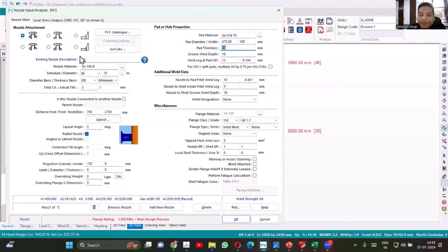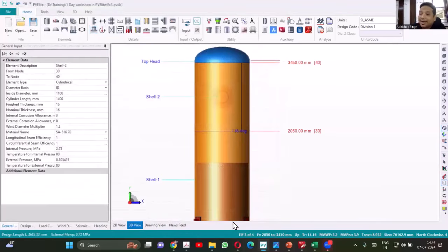So let us start from this point and go down. Then we'll go to RF pad. So this data is clear. Now I'll go to where I want that nozzle to be. You can change it, that is a selection. Normally we make nozzles from pipe, and pipes are available in inches, and that is the reason we normally select inch. If I want to change it, either I have to select that at the start, or I can change it by using this option.